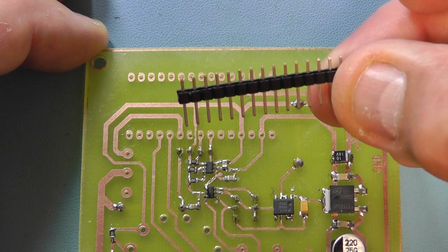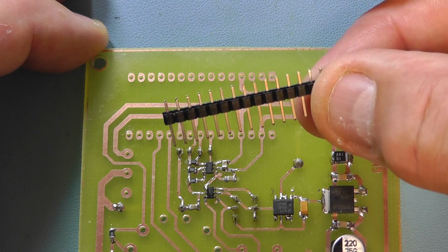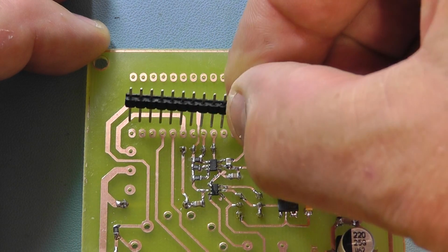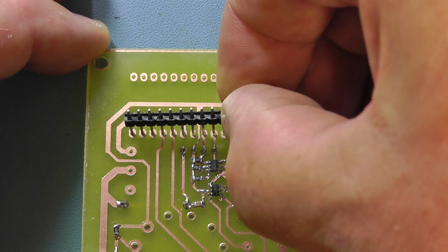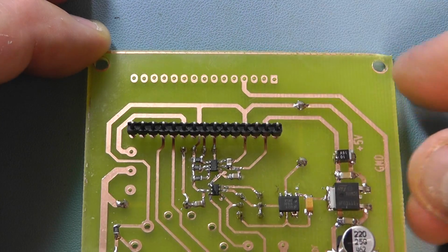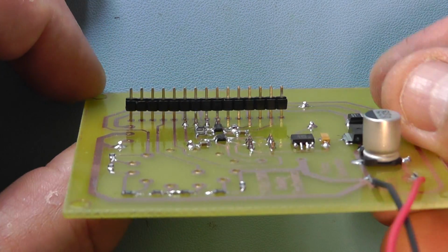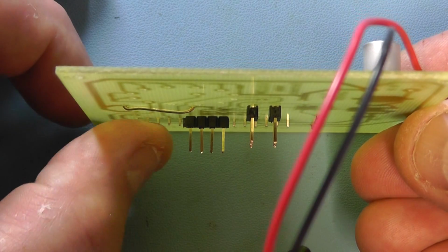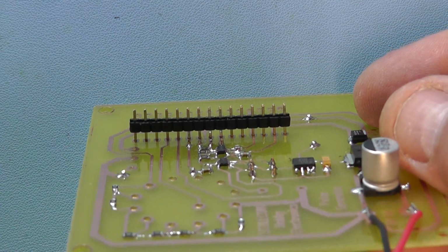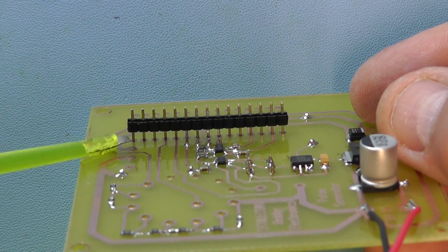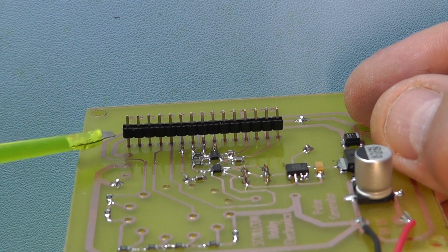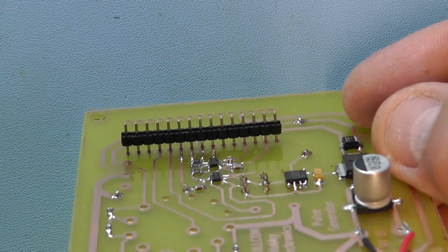What we're going to do next is I'm going to mount the pins. These pin connections come with the Arduino Nano, and the longest side of the pins I'm going to push through the slots on the PCB there, and just push it through until you can feel the pins there coming through on the other side, and that then gives you sufficient space to then solder the pins here on the print side of the board. So let me solder this one in here. I'll come back and show you that.